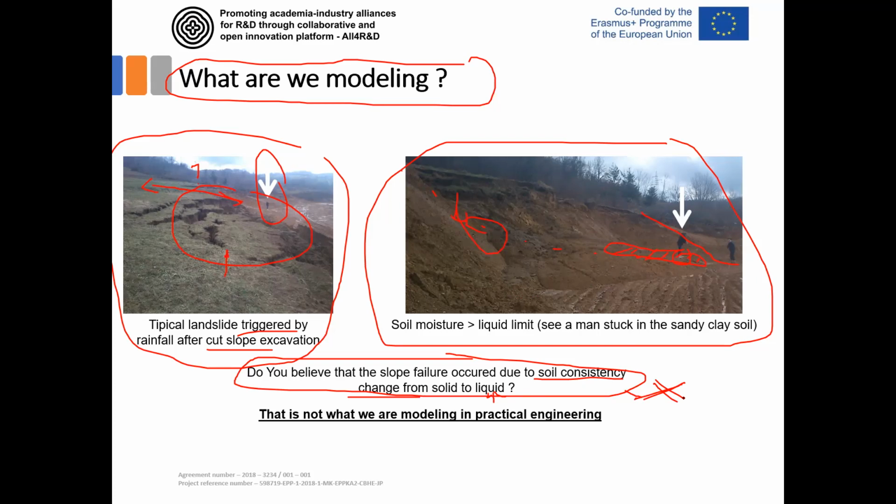That this assumption is not appropriate can easily be confirmed: when the soil is under pressure, like here, you have some surface, and then we did, for example, excavation here, and then the failure occurred here. So this sliding surface in this practical example is about 10 meters deep. Let's say 5 to 10 meters deep. That means that you have quite a lot of self-weight pressure where the sliding occurs.